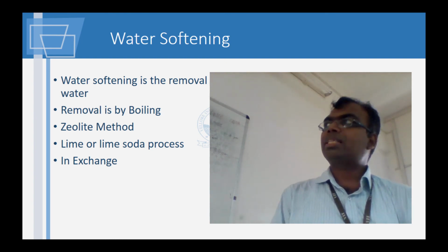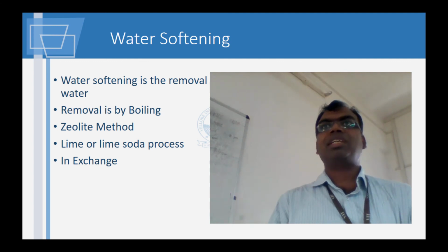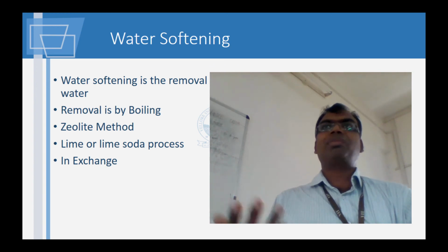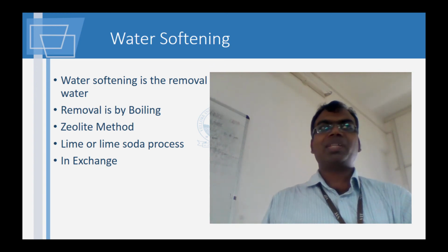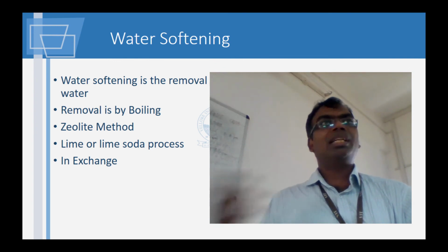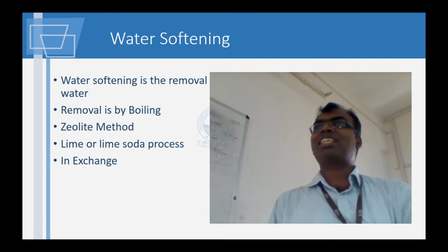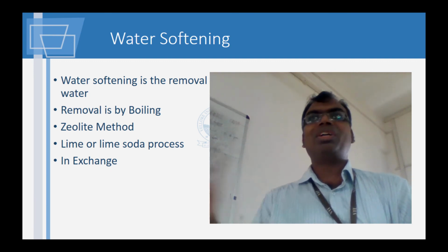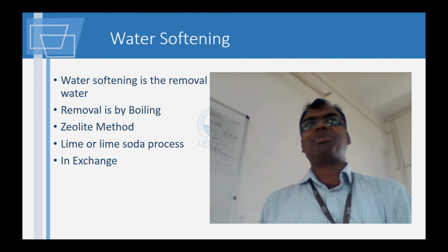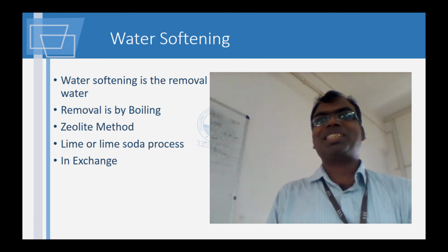In this unit, what I've not specifically targeted and told is disinfection, but disinfection is something which you've seen a lot in all of these videos. What are the methods? Basically chlorination. Then addition of potassium permanganate, KMnO4, is also one way of disinfection. Boiling is one, and UV light is another. Even ozonization is a disinfecting process. I'm not specifically talking about those things.